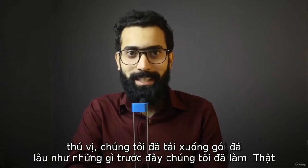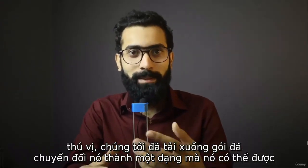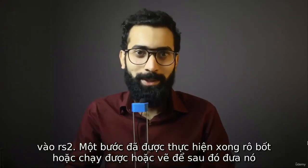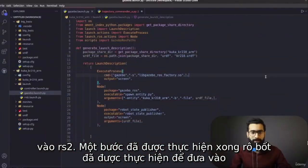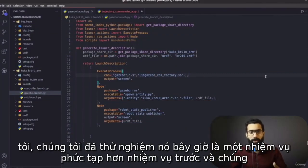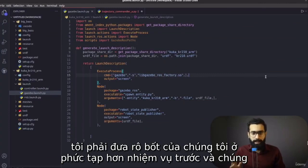So previously what we did was interesting. We downloaded the package, converted it into a form that can be executable or runnable on ROS2, then brought it into RViz2. One step has been done. The robot has been brought into a simulation, and it was working. Joint axes were working in RViz. We tested it. Now is a task that is more complex than the previous one, and we have to bring our robot into a working state in Gazebo.